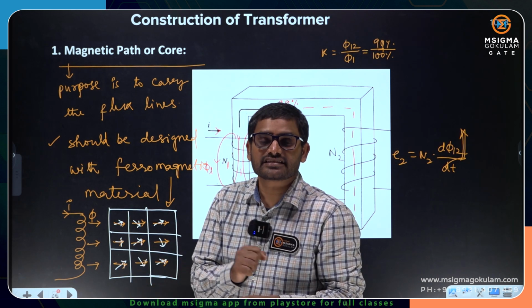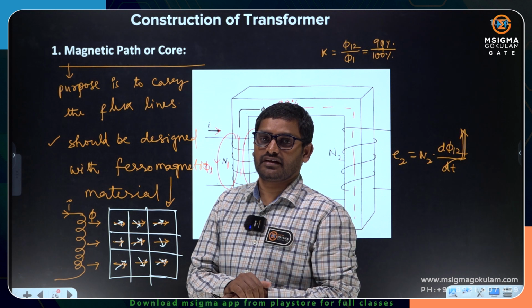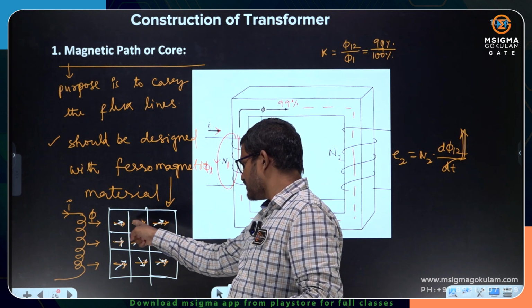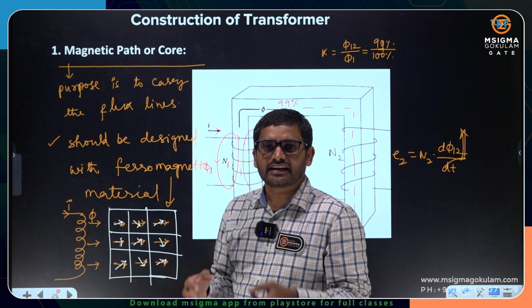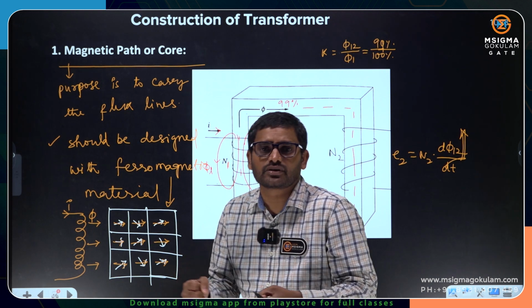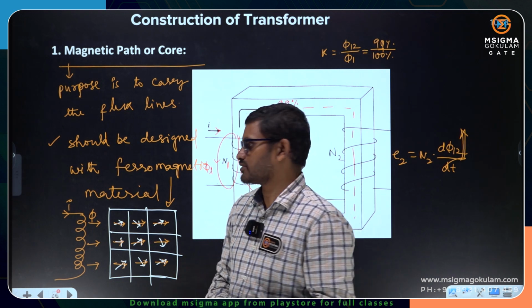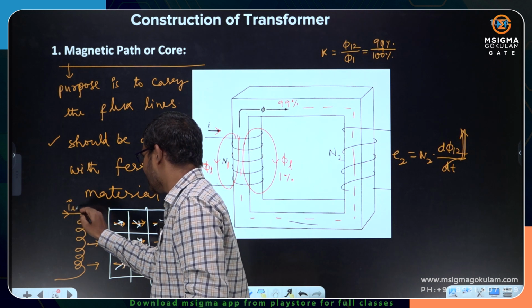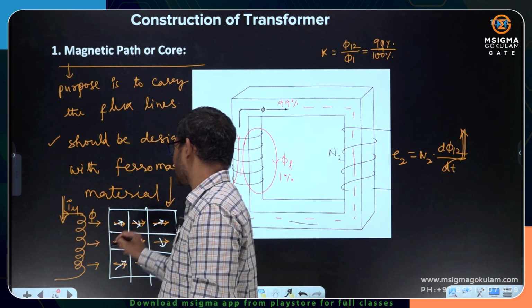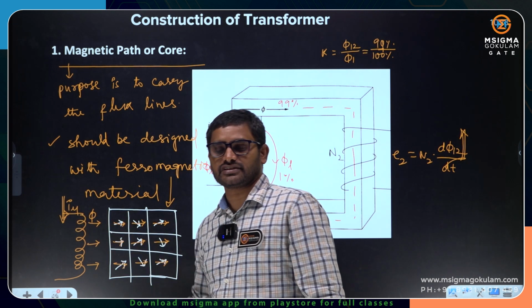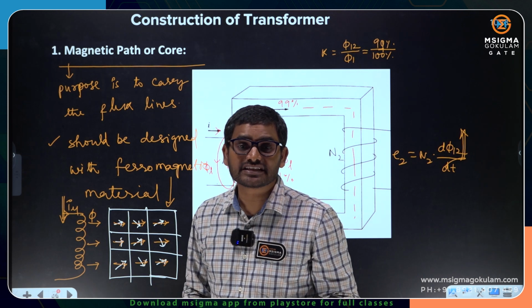That is what is called hysteresis energy or hysteresis loss. The dipoles can easily establish the flux lines, drawing a very least amount of force. The magnetizing current drawn is very, very less to change the orientations, because the permeability is very, very high.